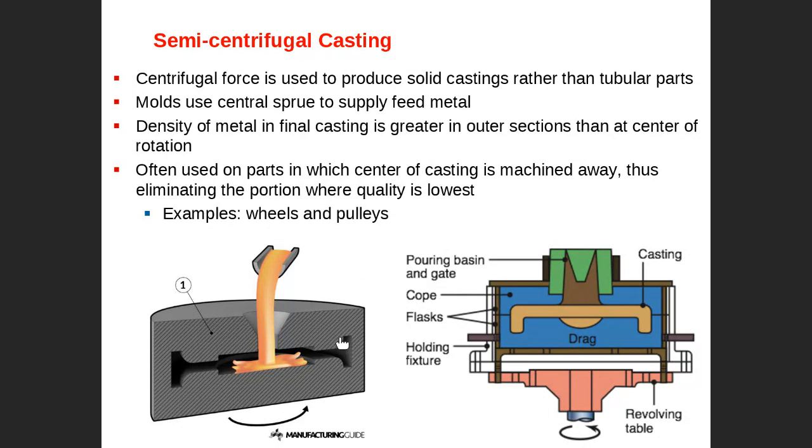What does that mean? It means that whether there is centrifugal force or not, the cast will happen. For example, like here, you put liquid; if this part is not rotating and there is no centrifugal force, the liquid will fill all the cavity and the cast will happen. No issue. So why do we use rotation here? We rotate the bar to push the liquid. It is assisting the casting process. Assisting here, not essential, but assisting.